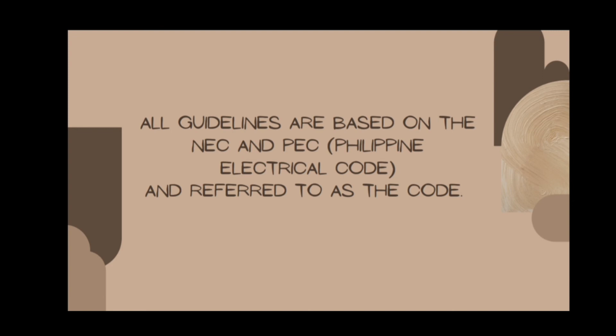4. Do not allow combination switch and receptacle outlets. Next, provide switch control for closet lights. Pull chain switch is nuisance. 6. Convenience receptacle should be planned properly, so that in case of failure of any one of the circuitry, the entire area will not be deprived of power.